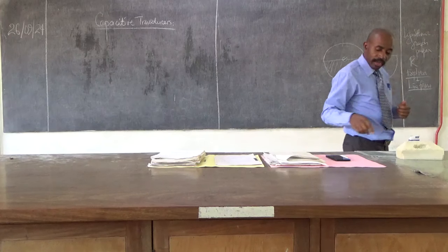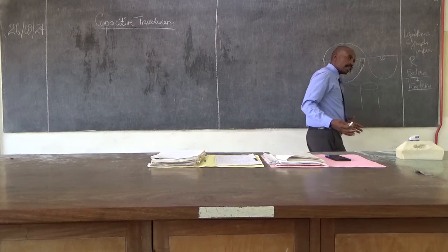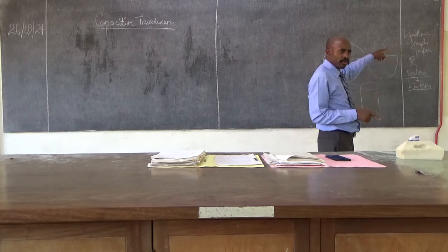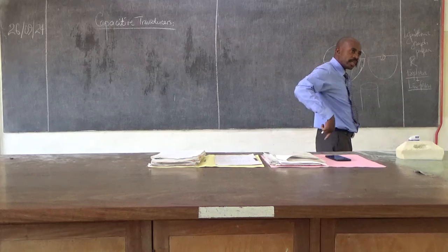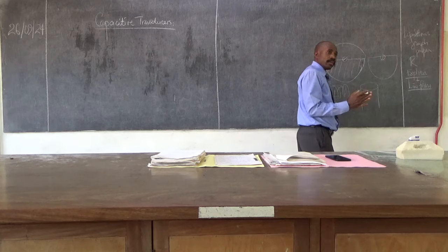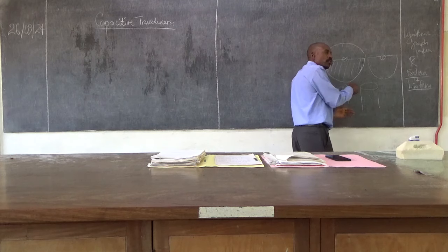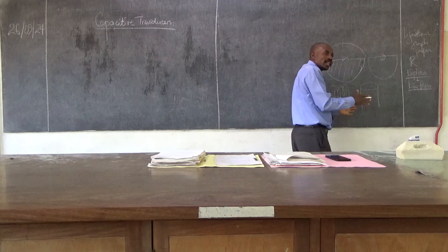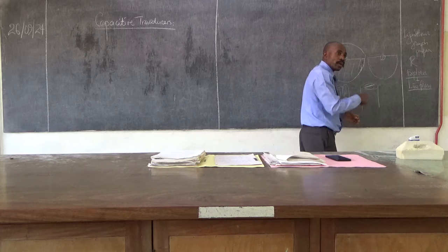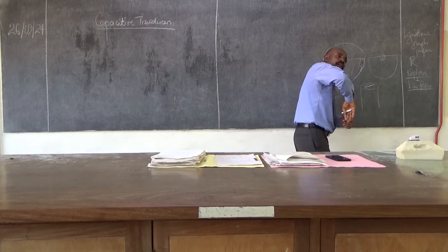But you also have other capacitors which are on the sidelines of the tuning circuit. There is one on the tuning, like there are 4 of them, if I am not mistaken, and then you have some which are on the side. You have an inductor which sometimes is waxed up so that the pitch does not change. And if you get a screwdriver and adjust the pitch, you hear the channels changing a little bit. And then some of these capacitors have a minus section where you can put a screwdriver and change it, and also adjust the capacitance.